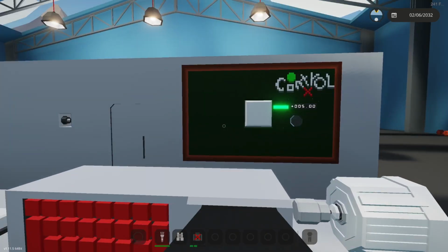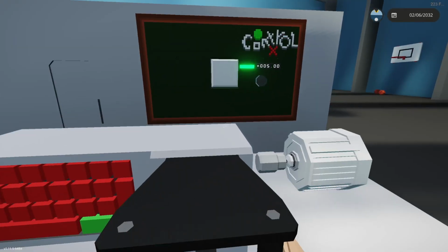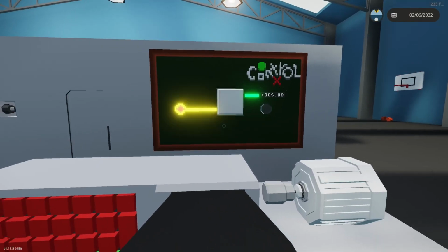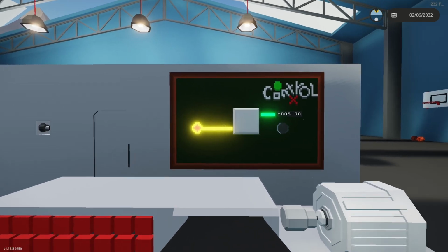Now, again, the space bar is for activate, the one is to reset, and we have 5 seconds on the clock. So I hit the button, as you can see it's active, so the timer is going to be going down, and then after 5 seconds, it turns on. Now here's the thing, I go to deactivate, it turns it off. Reactivate, it turns back on, because it's considered it is cleared through its duration. And it will stay like this until you hit the reset, at which point it will stay off until it manages to go through its duration while the timer is active.